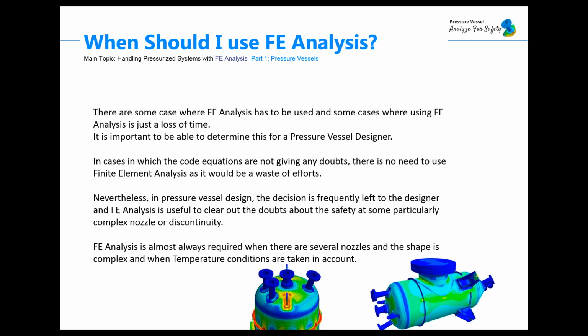But in pressure vessel design the decision is frequently left to the designers, and FEA analysis is useful to clear out doubts about the safety at some particular complex nozzle or discontinuity. Finite element analysis is almost always required when there are several nozzles and the shape is complex, and also when the temperature conditions are taken into account.